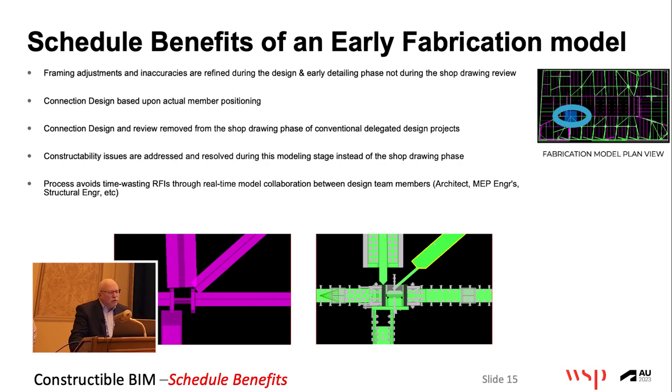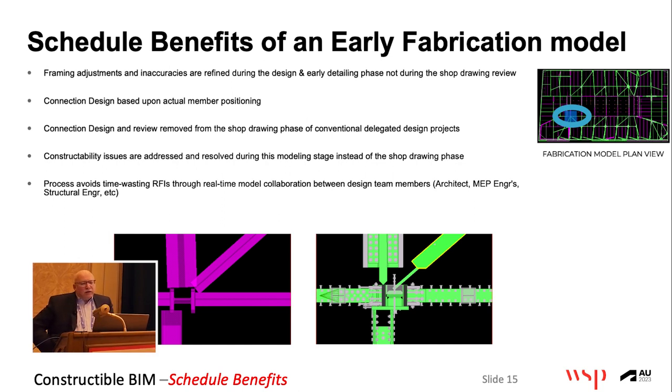This happens all the time with complex structure. And my point is really quite simple: do it during design, don't do it during shop drawings. Because then, of course, you're delaying the fabricator. The fabricator makes a delay claim. The delegated engineer who works for the fabricator has to redo things and is going to claim an extra. Just get it out of the way.